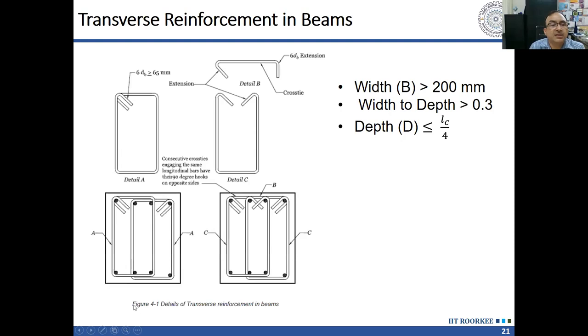Okay. Then these stirrup arrangements, how can we provide them? These can be either in the form of closed stirrups or closed stirrups and ties, or sometimes it may not be possible to provide a full closed hoop. In that case, a U-shaped stirrup and a tie is permitted by the code. It is permitted by the Indian code. It is now permitted by NBC also.